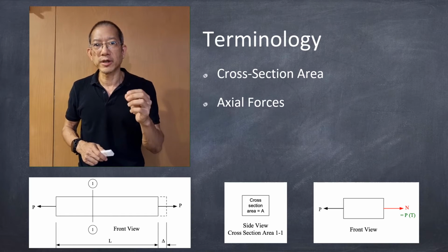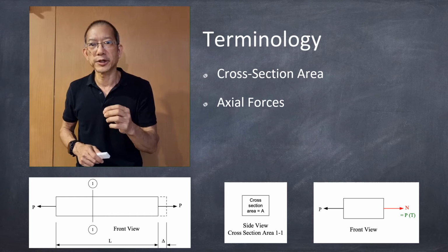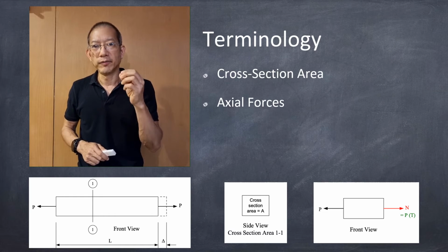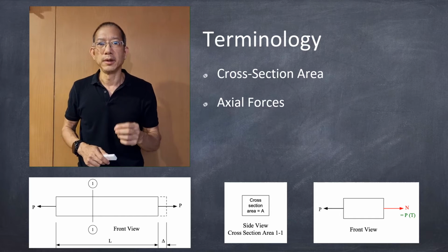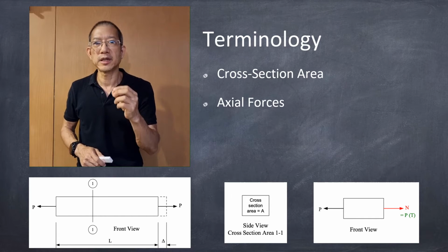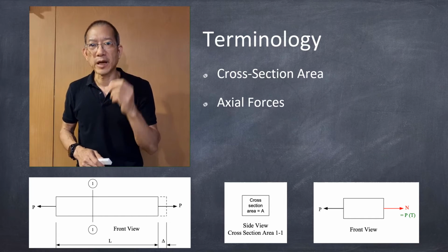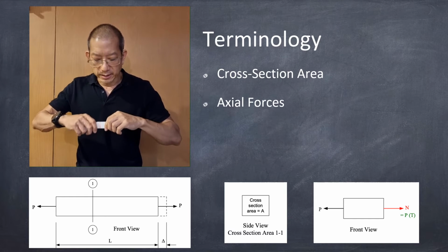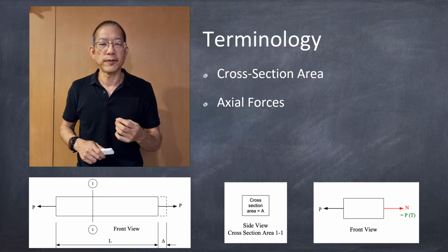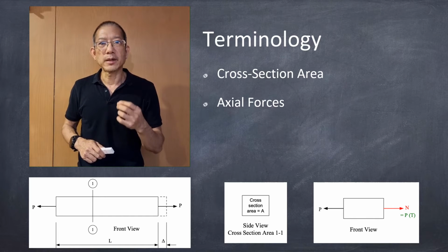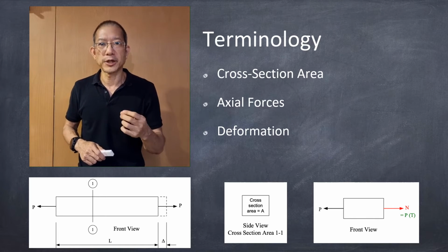When we calculate stress or even deformation, the capital N we use in those equations, or the force we use in those equations, will be the internal force, in this case axial force, not the applied force. In this case, it would be equal. In many cases, they are not. So be very careful.